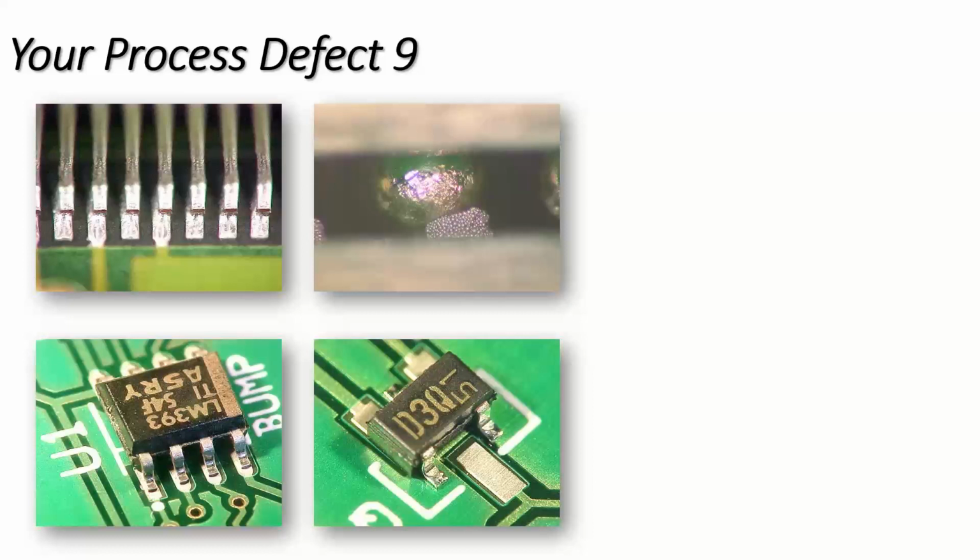And the data we're talking about in this particular case was the placement data files. Now, I've just illustrated here from my library just examples of a slightly misplaced QFP at the top, 2 components where we put the components in the wrong place, which are clearly obvious, and slight misplacement of the ball of a BGA onto paste. So they're just placement errors effectively. But the point is, is it right to modify data?